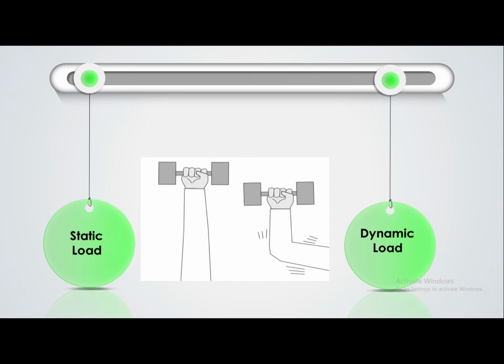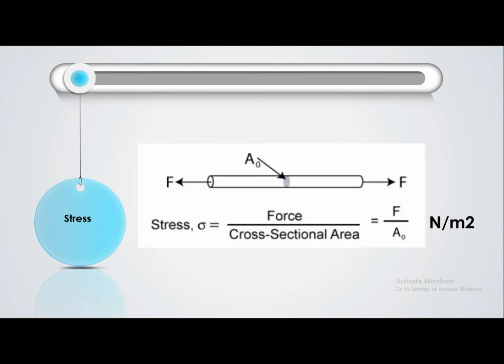There is an important note. If a material is subjected to a constant force, it's called static loading. If the loading of the material is not constant but instead fluctuates, it's called dynamic or cyclic loading. The way a material is loaded greatly affects its mechanical properties and largely determines how or if a component will fail, and whether it will show warning signs before failure actually occurs.